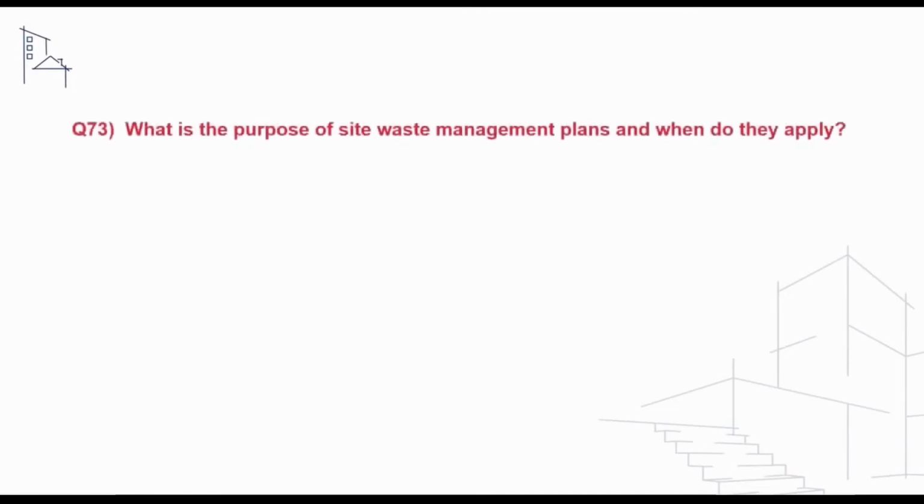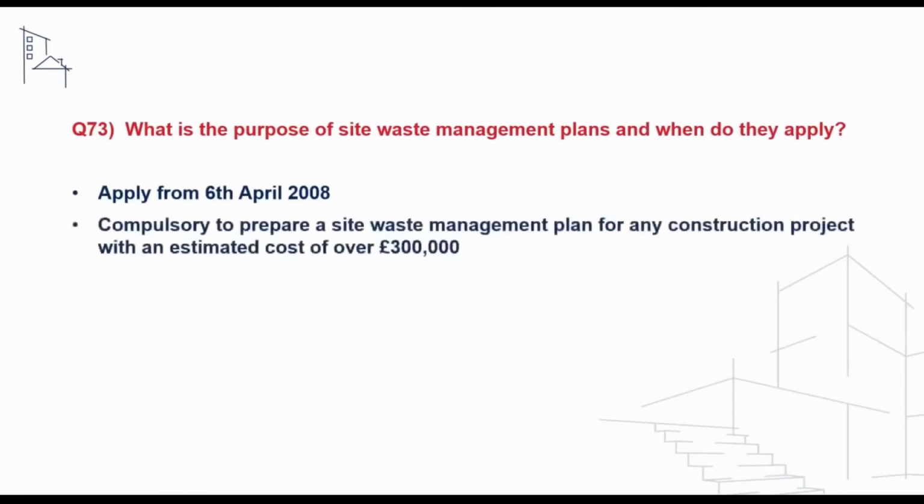We may also be asked a question on the purpose of site waste management plans and when they apply. And to address this, we could say that these came into force on the 6th of April 2008. And it is compulsory to prepare a site waste management plan for any construction project with an estimated cost of above £300,000.